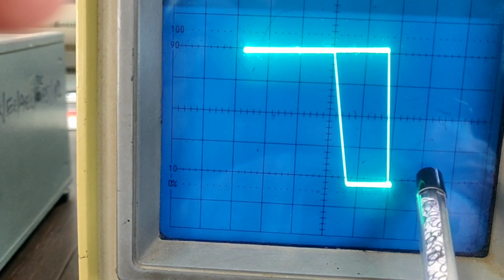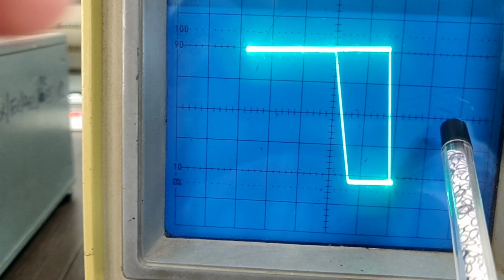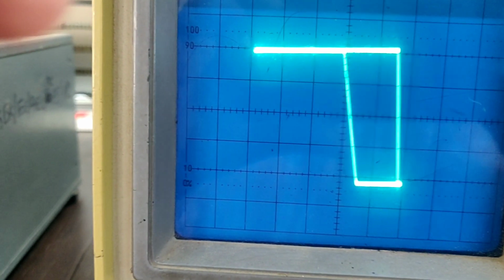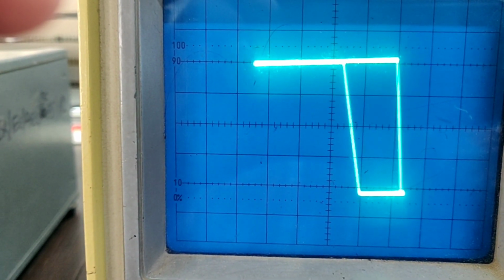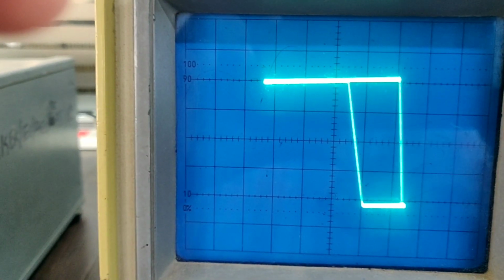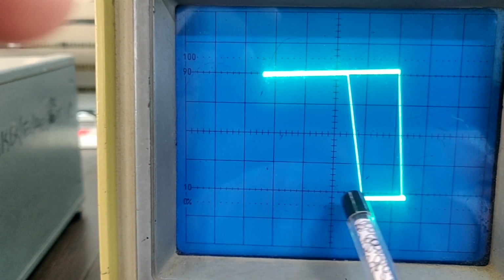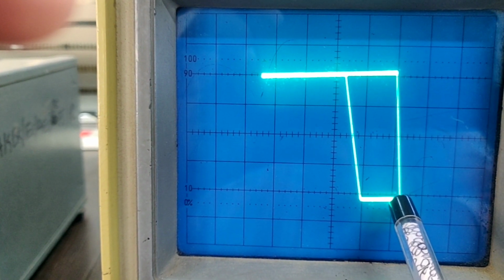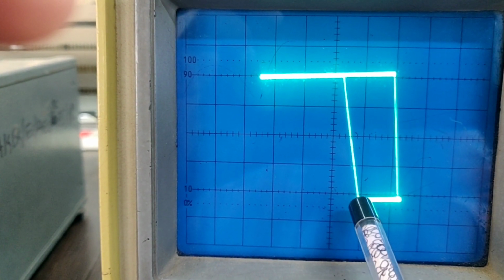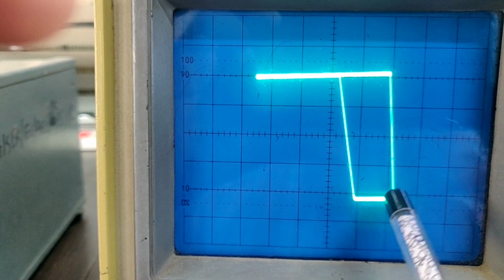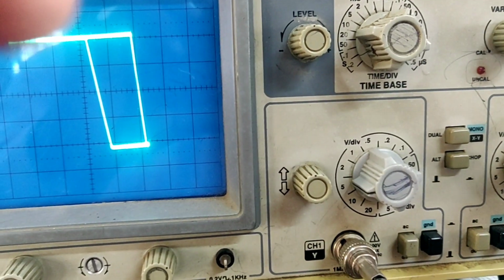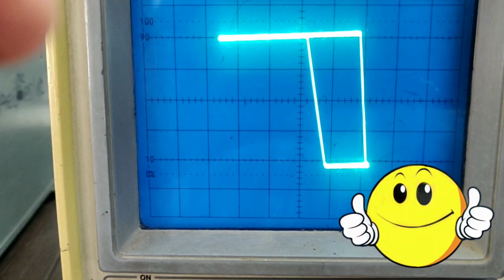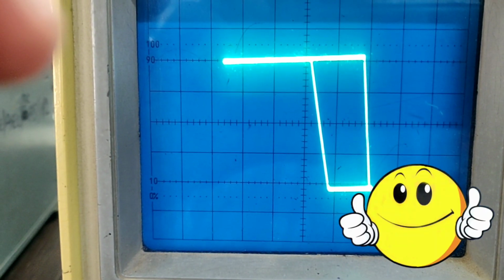You see that here it is completely shifted towards between the first and second quadrant. So both are on the positive side because our design is plus 2 volts and minus 2. Here you can see there is 1 division for LTP and 2 divisions for UTP. So that means 1 into 2 volts and 2 into 2 with respect to the volts per division reading, it is plus 2 volts and plus 4 volts. So this is another way of displaying LTP and UTP.